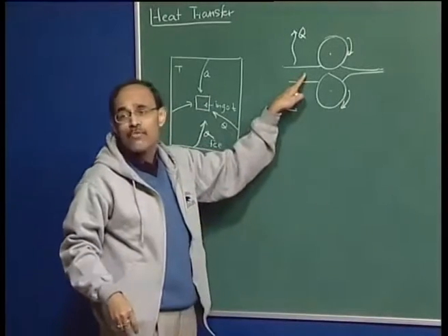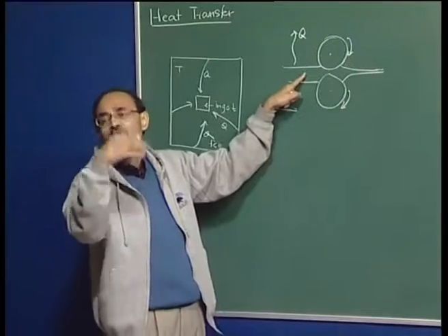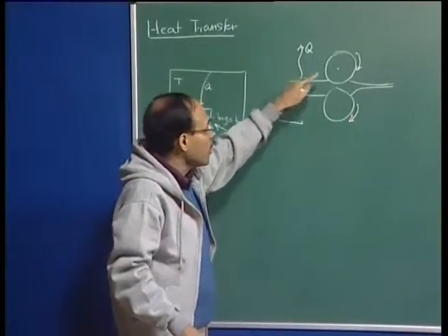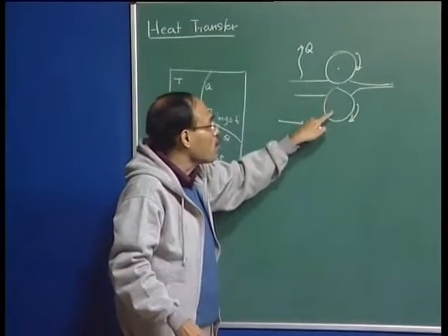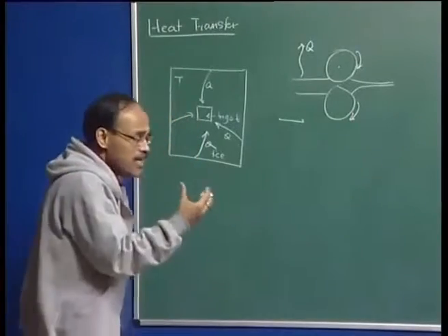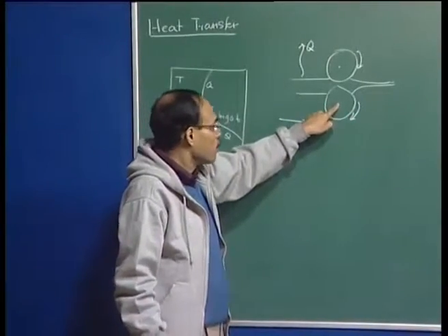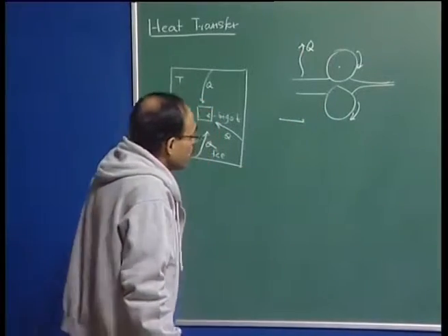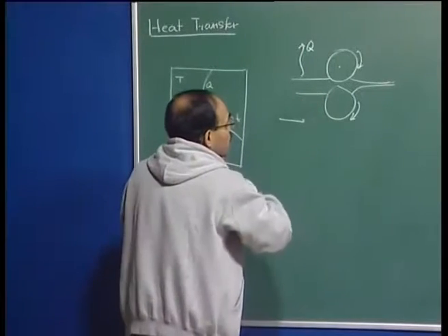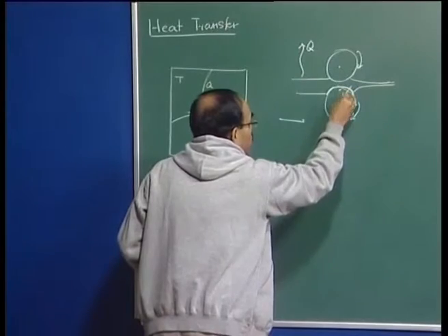Then there is heat evolution within the solid because of mechanical working, the conversion of mechanical work to heat energy, where an efficiency factor is involved. And then there is contact between the roll and the solid. This roll is always water cooled to maintain a relatively low temperature, to maintain its low deformability, and to have good heat transfer rates. So, we have heat flow from the solid surface into the roll.